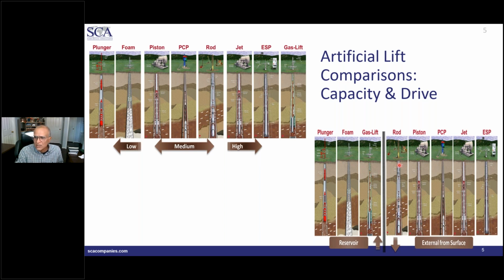Whereas in the case of rod lift, piston, jet pump, PCP, or ESP, in short, whenever there is a pump in any of the lift method names, meaning you are lowering some device inside the wellbore or inside the tubular, it is energized from the surface, and that is what provides the necessary dynamic head for the fluids to come to the surface.